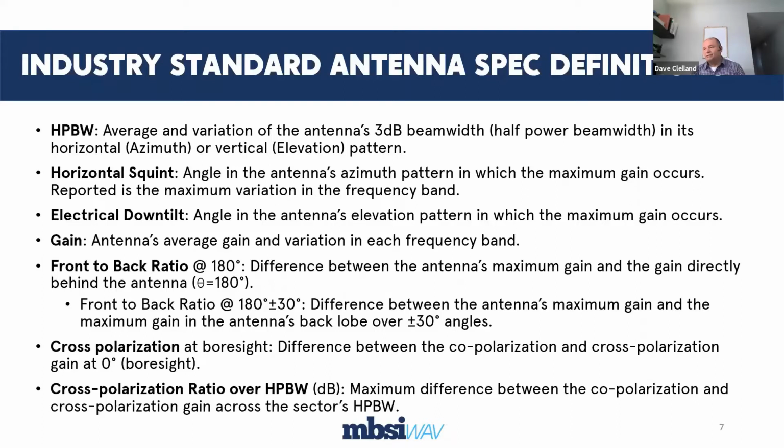Also, antenna manufacturers that make electrical down tilt antennas like this also make them motorized, remote control, so that the down tilt is varied by a controller in the site. These antennas, of course, are much more expensive than a fixed tilt antenna, but nevertheless, there's use for them. In the fixed broadband world, not so much, but in the cellular world, in urban environments, variable down tilt antennas are used quite often.